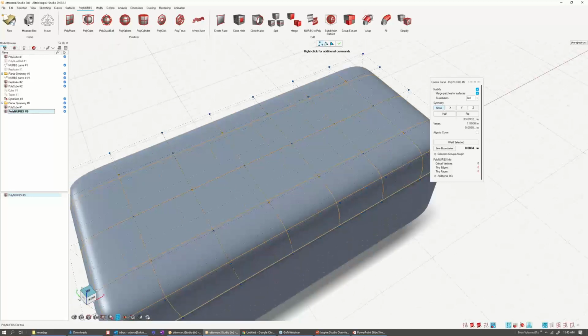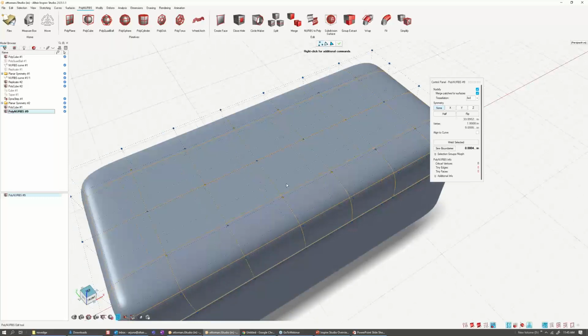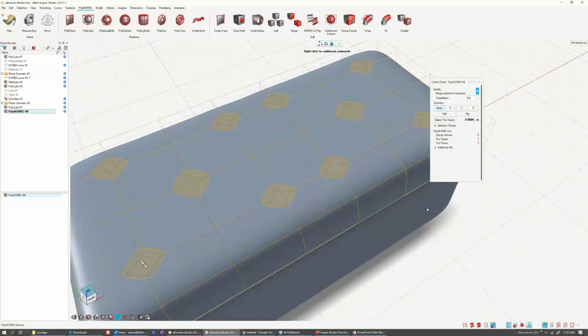Once you have these selected, I can right click and say chamfer, and click and drag this to chamfer it out. So I've created the chamfer of all of these. Of course I didn't have an odd number along the x-axis, so that's why it looks funny. But once you have selected the chamfer, you can hit D and it will quickly turn it into a face selection. With the face selection, I can just push this down to create the dimple. So here I'm pushing it down.